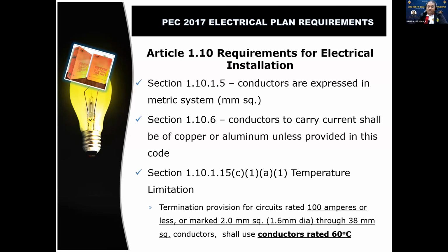And then temperature limitation. So yung termination natin for circuits, no, sa mga 100 amperes or less or marked sa wire size na 2 mm squared, no, yung conductors natin are, unless specified, no, are rated at 60 degrees, no.